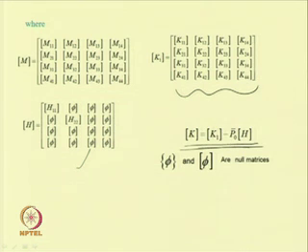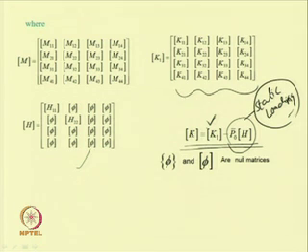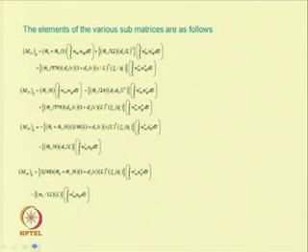It may be noted that this term comes from the stiffness, but this term is coming from the static loading. So, the static loading influences the equivalent stiffness of the system, and one can similarly find the modal frequencies for this system. Modal frequency can be obtained by finding this K inverse M. So, let us first see what these terms are. What M 11 stands for. All these terms can be written, for example, M 11 i j, that means i equal to 1, j equal to 1 also one can take, or this i and j vary from 1 to 4.